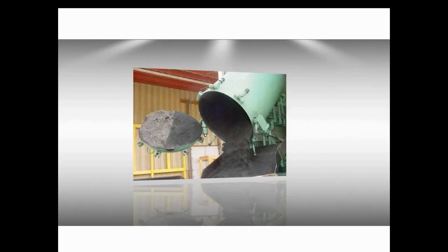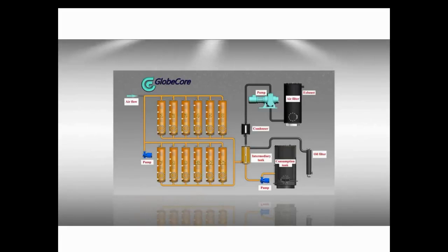But the problem was that the Fuller's earth thrown away usually contained 6% of oil, which had its cost. So operation became expensive and environmentally unfriendly, as rains drove oil from the disposed Fuller's earth into subterranean waters, and that brought negative results. New machines provide for reactivation of Fuller's earth.